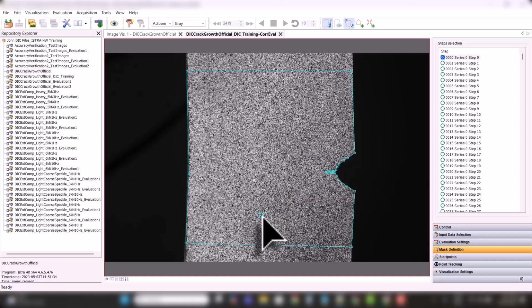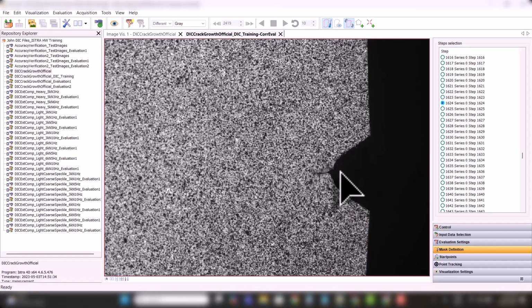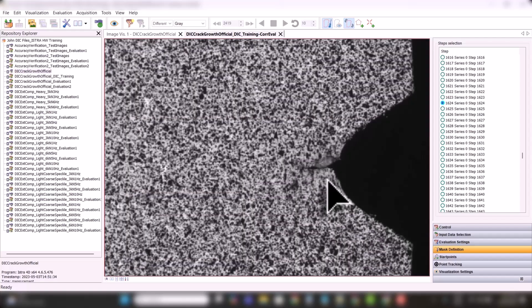And we'll start with the crack tip refinement. And so I'll just go ahead and leave the rung steps. You could potentially consider starting the analysis from scratch here and reasoning through if you want to add rung steps, but I'll just go ahead and leave them.